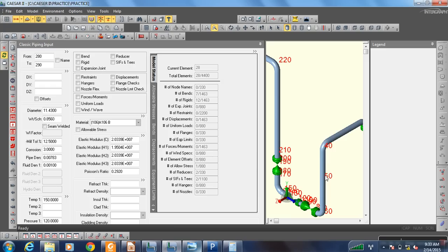So that part you break up here, that pipe at 50 node. So from here, you see this 280 is the last point there. We have drawn this followed by node, so here that node is 280. Now the next node that will come is 290 or any other. But we need a pipe from here, 50. Just remove this 280. Go to here, 50. This thing let it be anything, right? Whatever is going on, let it continue.